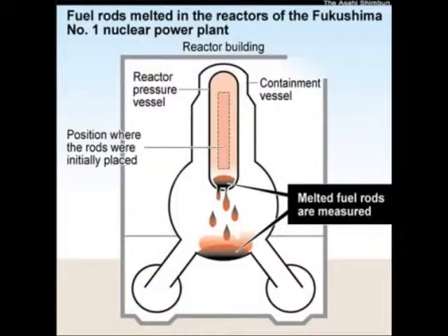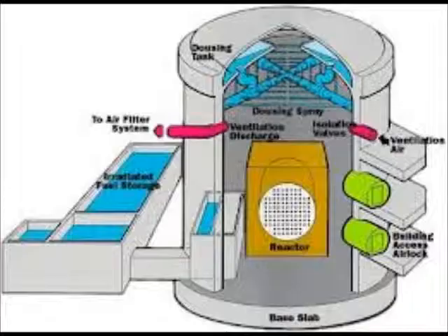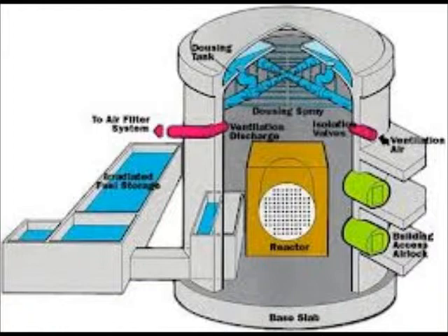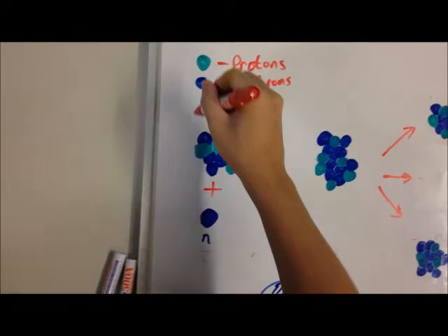Pressure vessel or pressure tubes, usually a robust steel vessel containing the reactor core and moderator/coolant, but it may be a series of tubes holding the fuel and conveying the coolant through the surrounding moderator. Containment, the structure around the reactor and associated steam generators, which is designed to protect it from outside intrusion and to protect those outside from the effects of radiation in case of any serious malfunction inside. It is typically a meter-thick concrete and steel structure.